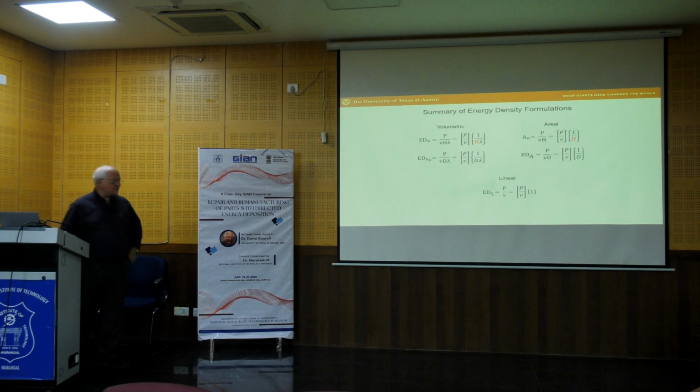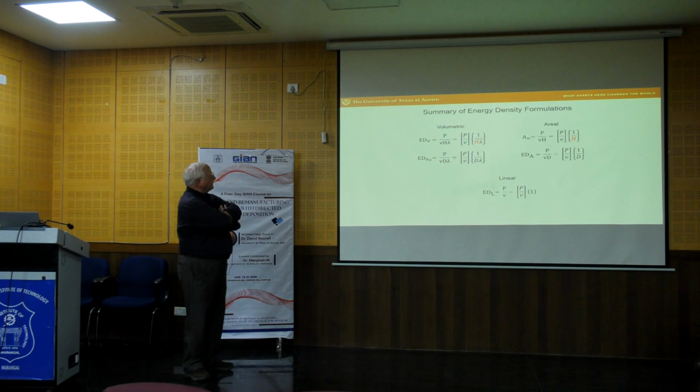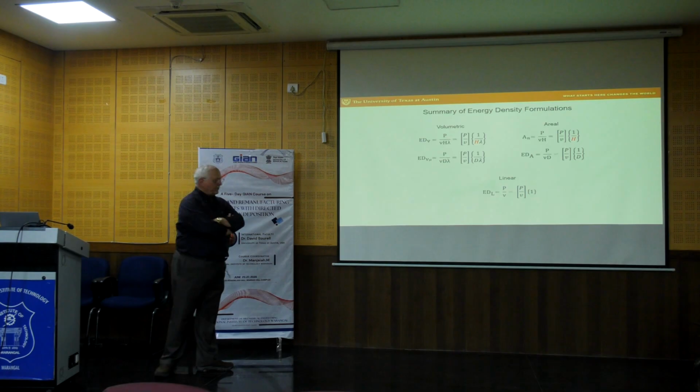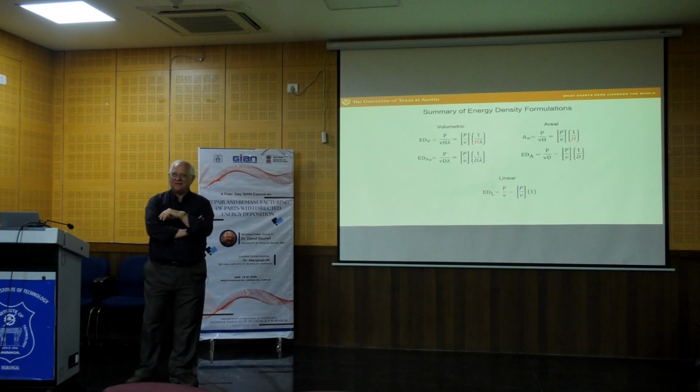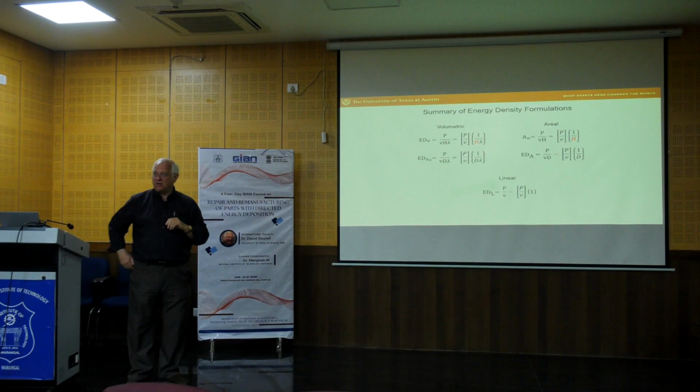So if we look at these five forms, there's a commonality to all of them, and that is they all involve the power divided by the velocity. So power over scan speed is the same for all of these.